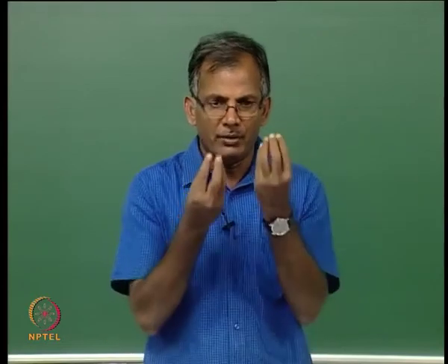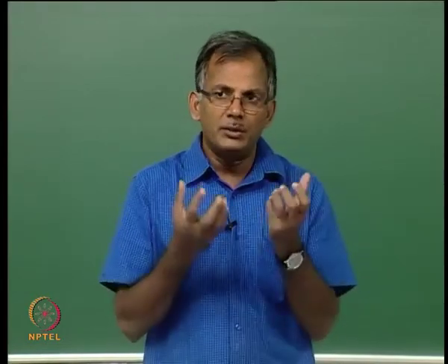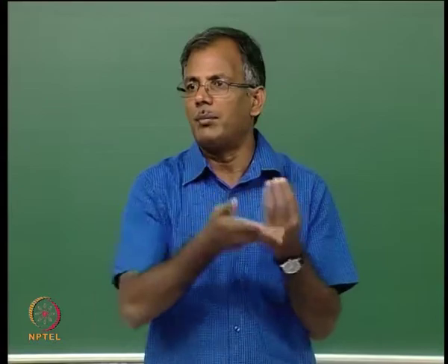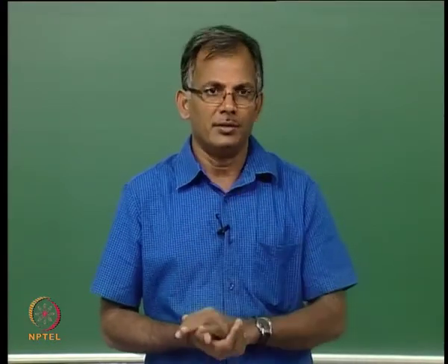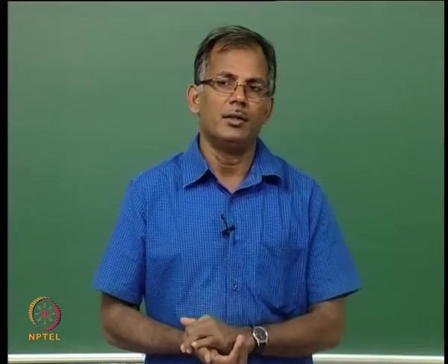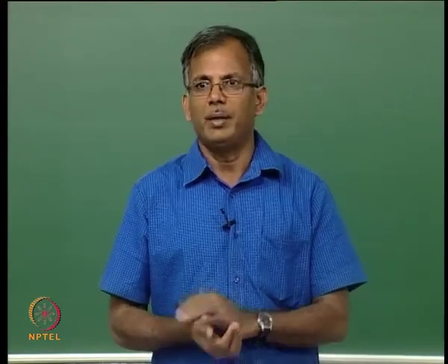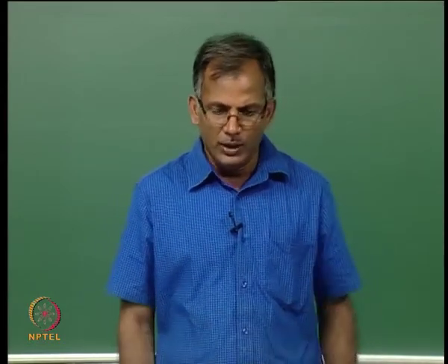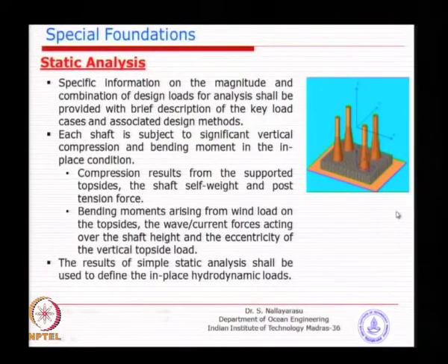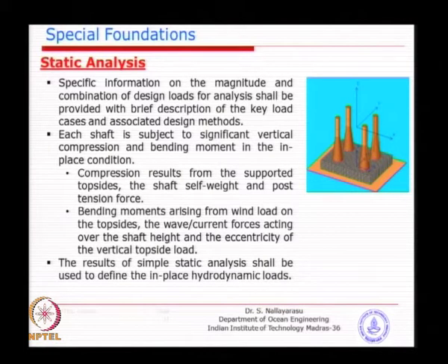So we have to devise a methodology by which soil springs can be modeled at the bottom of the foundation, and they cannot take tension, very similar to what we were doing for mud mat. But for mud mat we go for a simplified method, not using pile soil interaction. So doing a simplified service analysis is going to be the case. You can't do a complete nonlinear analysis.